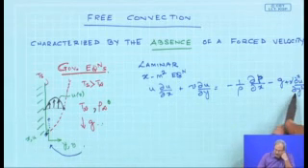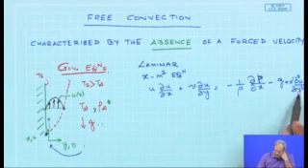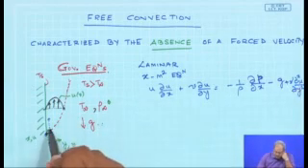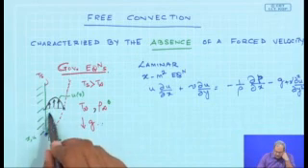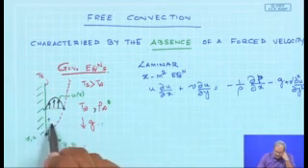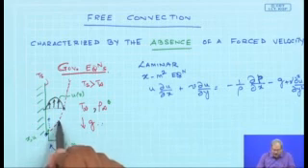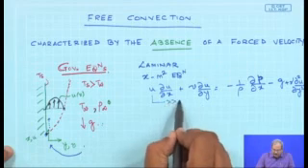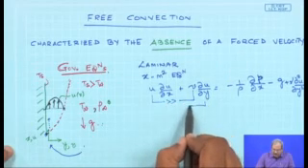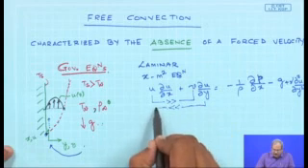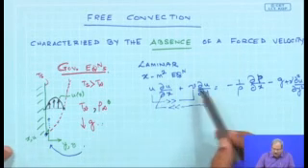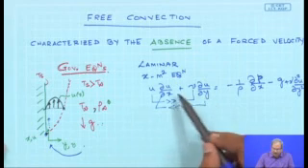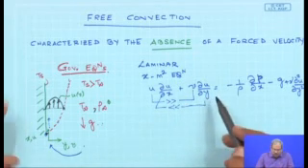Note that I have neglected the viscous transport of momentum in the x direction, as the velocity gradient in the x direction is very small as compared to the velocity gradient in the y direction, due to the thinness of the region where this flow is taking place. However, u is large as compared to v, but ∂u/∂y is very large as compared to ∂u/∂x. So with the simple boundary layer approximations, none of the terms on the left hand side could be neglected.